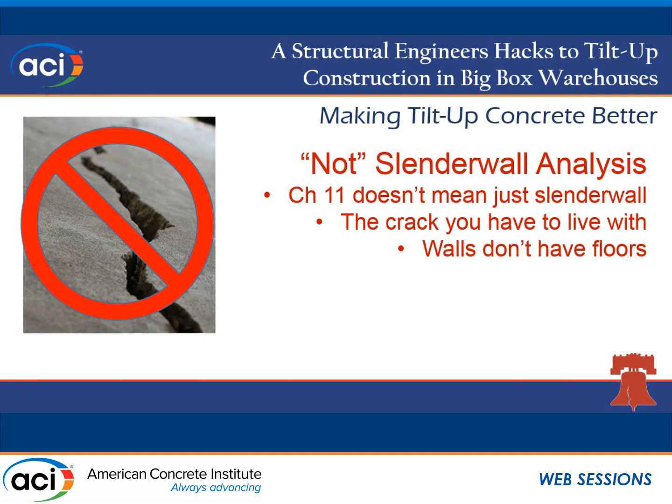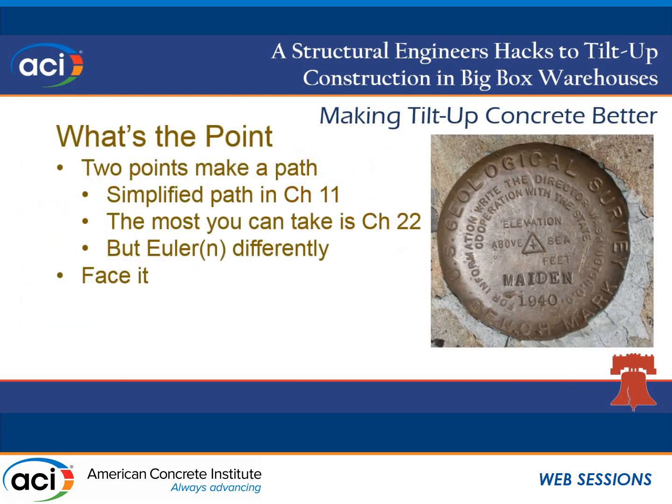And then when you do get into columns, probably the biggest thing to look out for when you have an axial load greater than 10% is that in slender wall design, you can spread that load out, right? As long as you don't have a jamb or anything, you can keep widening the load until you get enough panel to get to 6%. But sometimes you're restricted by jambs. When you're stuck designing something as a column, even if you have concrete for 100 feet in both directions, ACI says you can only treat the column as the area of the cage plus 1.5 inches on both sides, which means if you're greater than 6%, you may get stuck with something that's only 18 or 24 inches wide, where slender wall would have been okay.